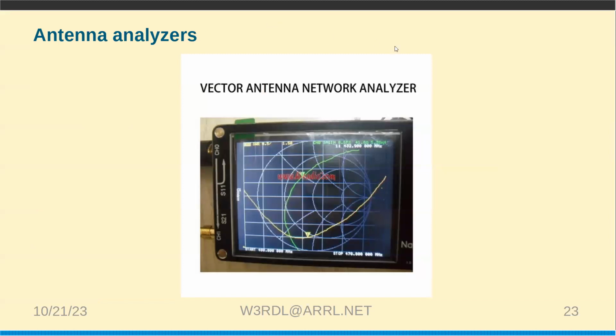There's a picture of one of the typical nano VNAs. And you can see the two ports, channel 0 and channel 1. And we'll talk about those a little bit, where in this one, it's showing where you do an S21 or an S11, which are called scattering parameters or S parameters.